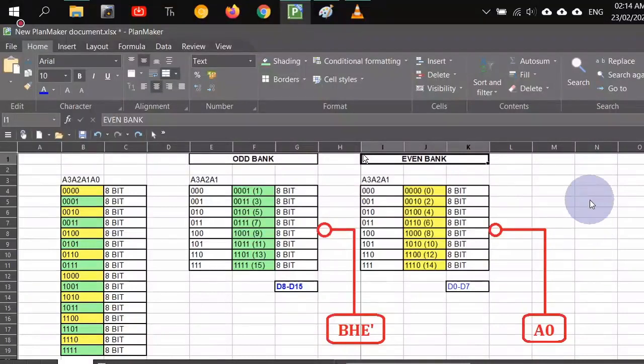So assuming that we have got address lines only from A0 to A3 in one microprocessor, you could either purchase this single memory chip which will have 16 memory locations. Every location will be of 8 bits or 1 byte each, and you can interface it to the microprocessor. But if that microprocessor is a 16-bit microprocessor, that means the data bus of the microprocessor is 16-bit. So at one time the data bus can contain 16 bits of information, and if you intend to write that 16-bit information in one machine cycle, with this structure of memory, it is not possible.